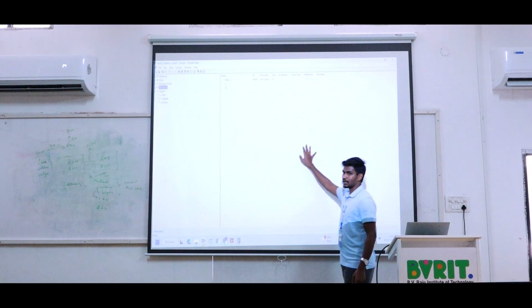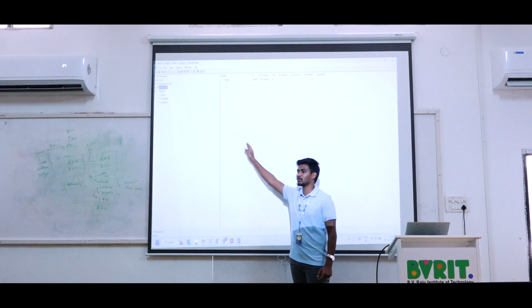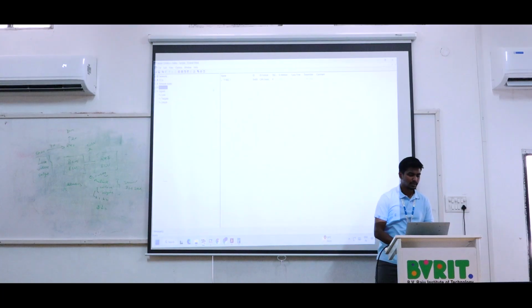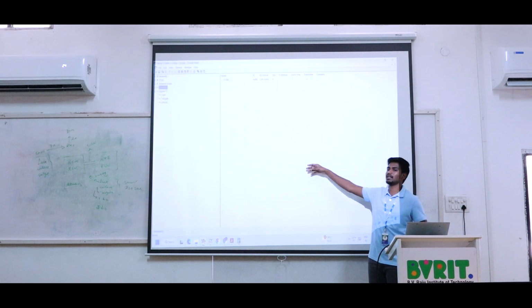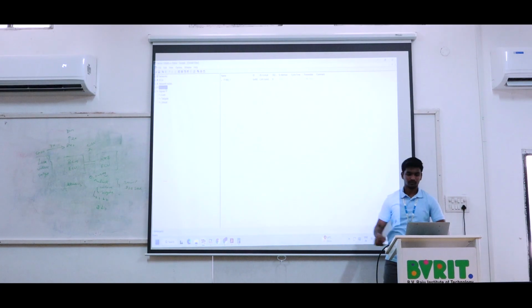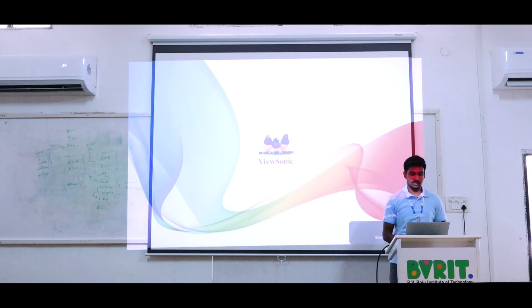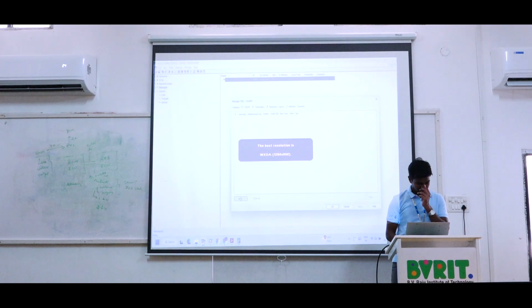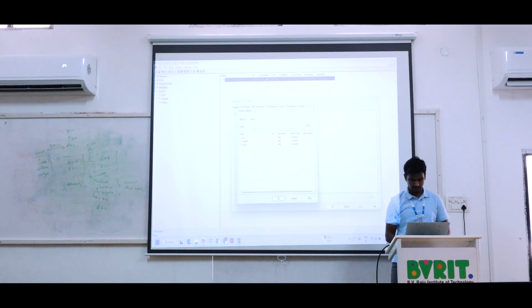This X mark shows that this message has no sender node and no receiver node. Whenever we find these X marks, the signals are not mapped to any messages. So the message is showing this because it is not mapped by any transmitter or any receivers. Just right click and then open the signals. You can add the signals we need. Okay, so now signals are mapped, going to apply.